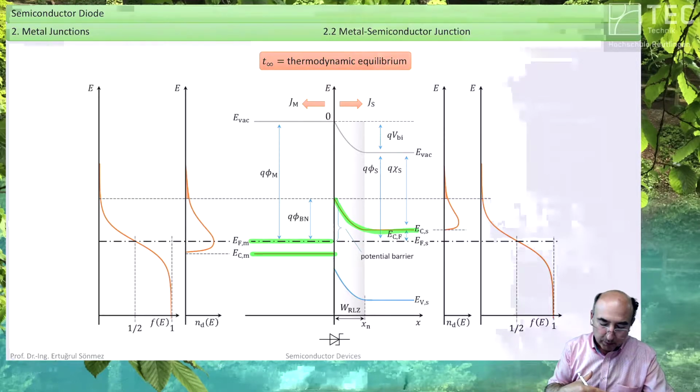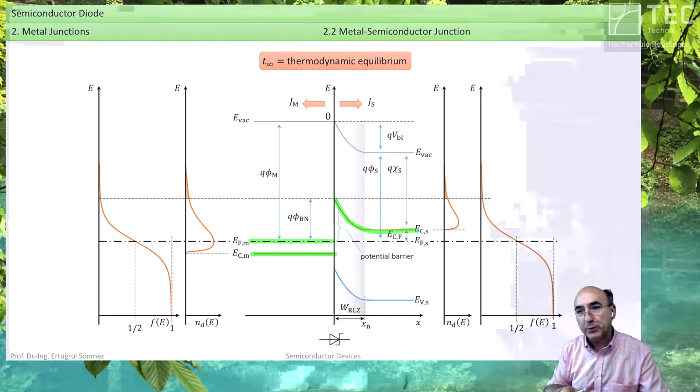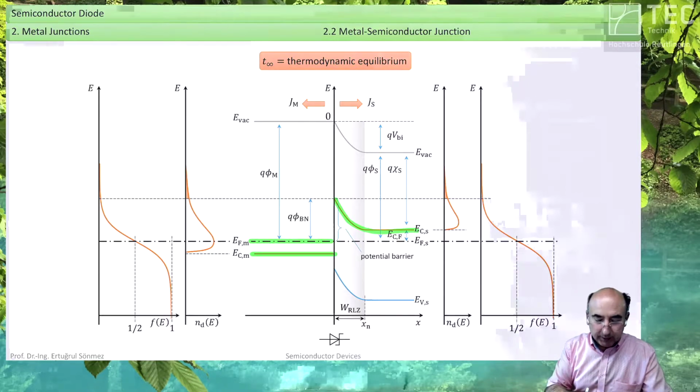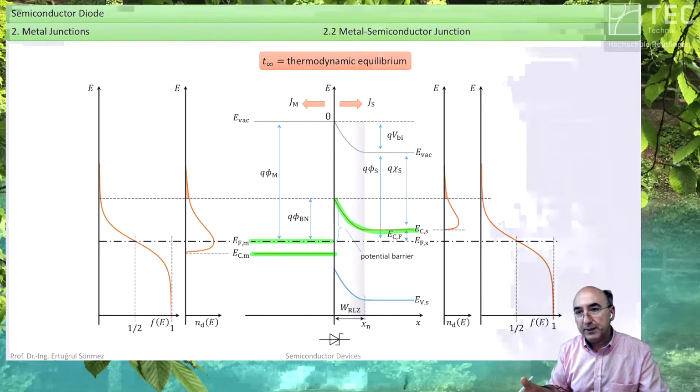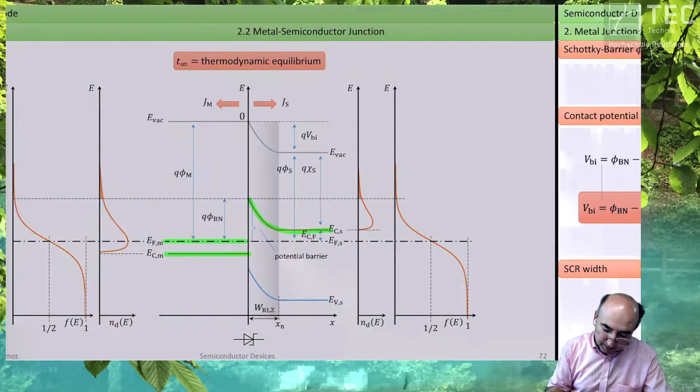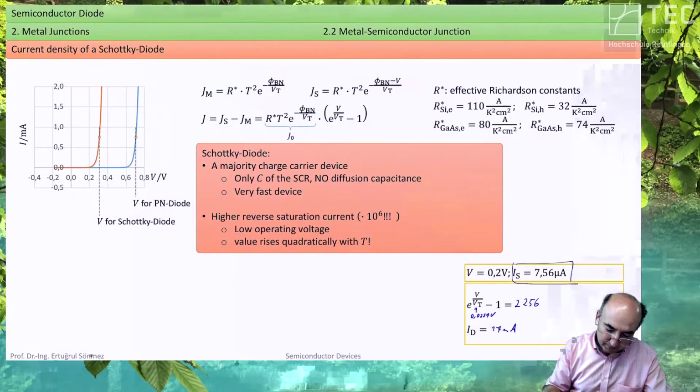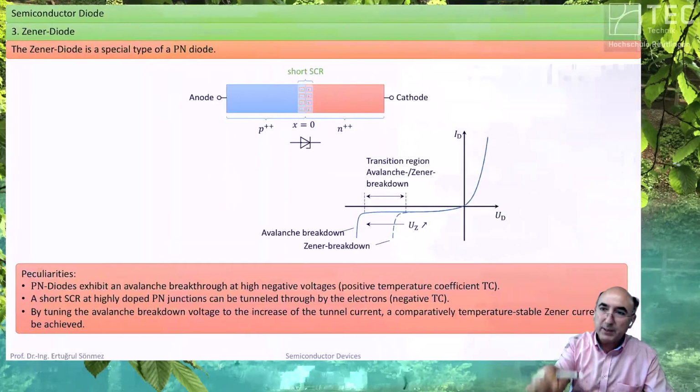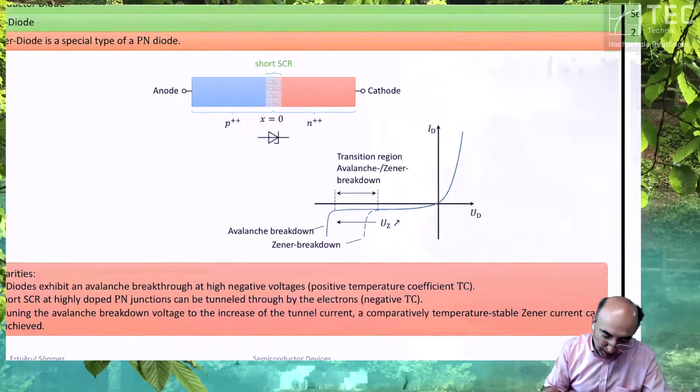Let's say you would like to withstand 5 volt, then the Schottky diode withstands 6 volt or something like this, but it can vary. But if you buy a Zener diode, it is designed, or at least picked from the production, for a value. Okay, how does it happen?